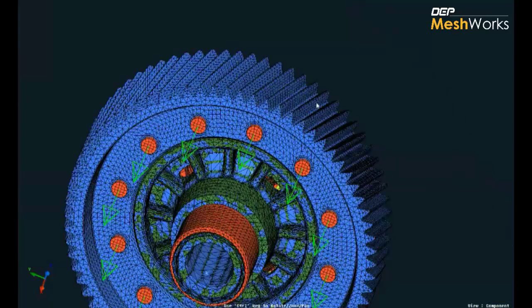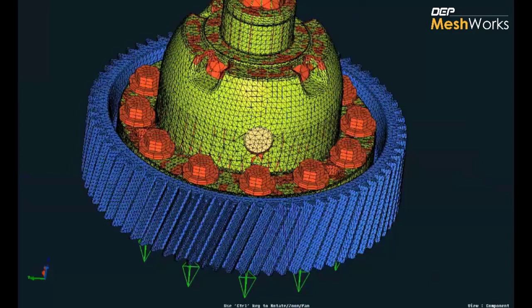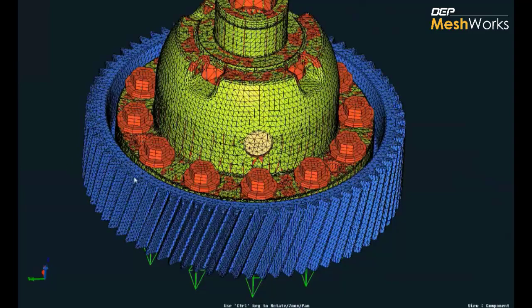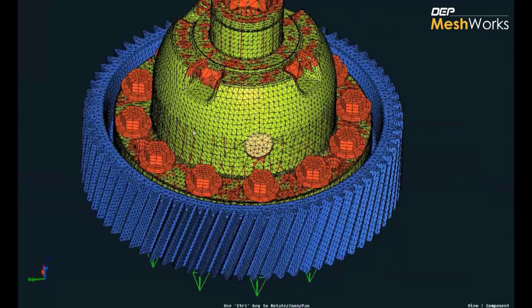Here I'm not going to worry about the modeling part, which is the bolt connections, and then again the solver attribute files. I'm not going to worry about these, I'm just going to do a part swap scenario. So I'll just mention what is the new part and what is the old part, and just say generate an Abaqus model. It identifies internally all the dependencies like the contacts, surfaces, element sets, node sets, which are used for all our post processing, and then it updates them automatically.